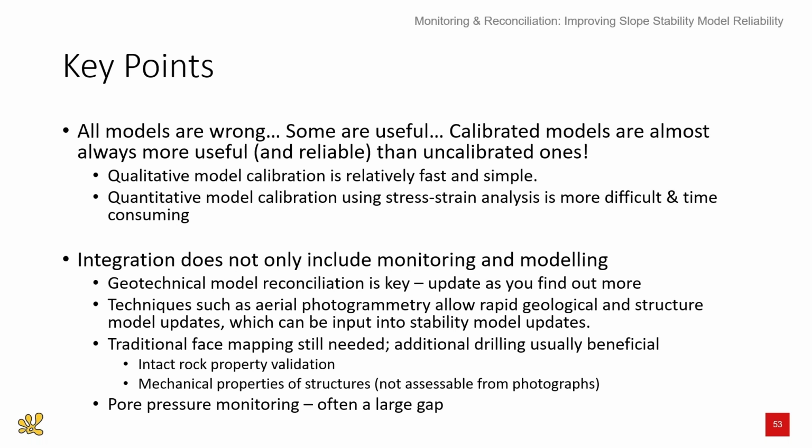Traditional face mapping is still needed, especially for our intact rock property validation and our geomechanical properties of structures, which aren't accessible from photographs. Fault pressure monitoring we found in many mines is a gap, but something you can also remediate.